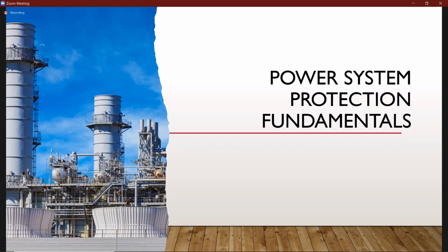And some persons did a fairly good job in terms of the theory, where they explained that whilst you may solidly ground a transformer, you don't want to do that for the generator, because in doing so, the high fault current that will flow through can easily damage the generator. So we earth through an impedance to reduce the fault current flowing through the windings of your generator. But of course, that has to be managed, and one will expand on that from a protection standpoint.